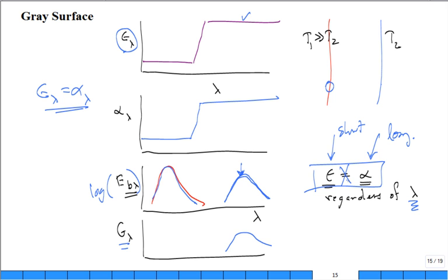Actually, engineers exploit this. You probably have seen something like that. You want a good solar collector. What about the photons? We'll talk about the wavelength of the photons from the sun coming in, short wavelength. Make a material that grabs them, absorbs them. But now that you've gotten it hot, it wants to send out its own photons. True? But it's not going to be sending them out at 5,800 Kelvin.